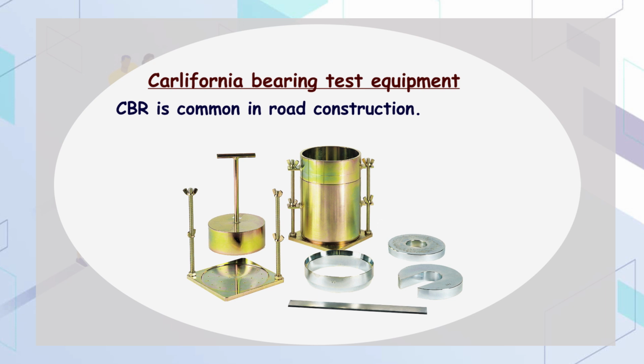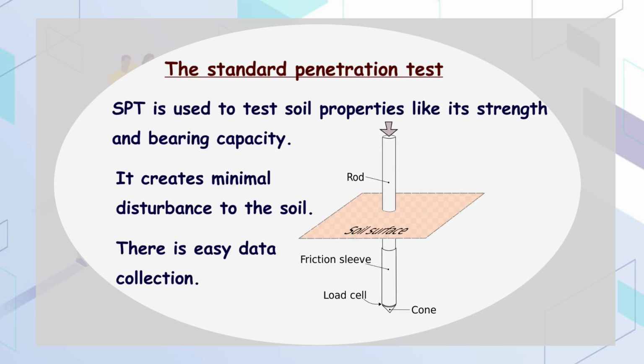We have the DCP, dynamic cone penetration testing, for assessing soil properties, particularly its strength and bearing capacity. It is favored for its real-time data collection and minimal disturbance to the soil.